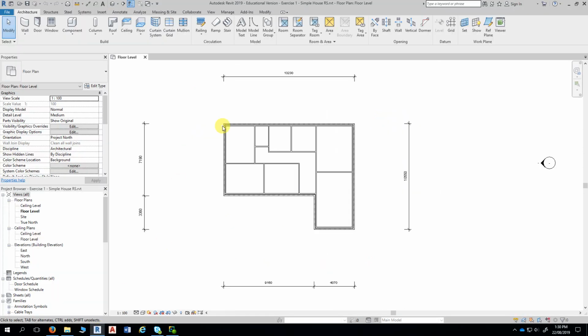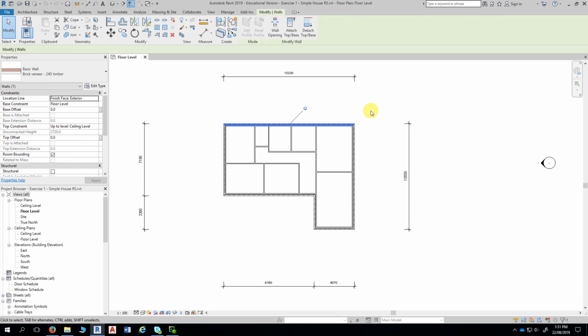These are real dimensions that we would use in our final floor plan, but here I call them working dimensions because they assist me in setting out the initial external walls. One of the things we did with the walls once we got the set out correct was we pinned them.